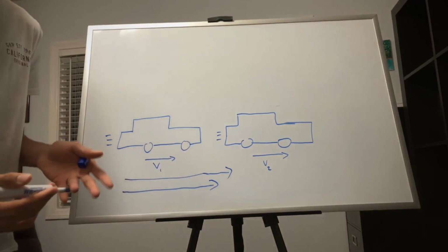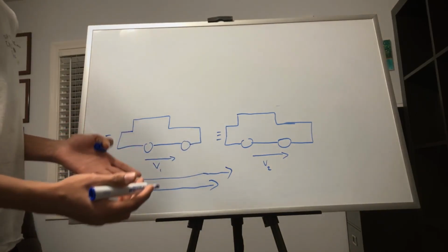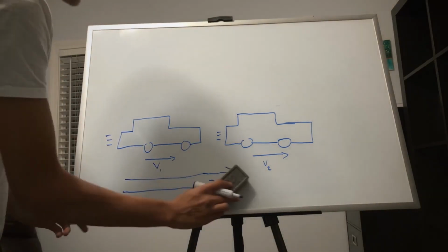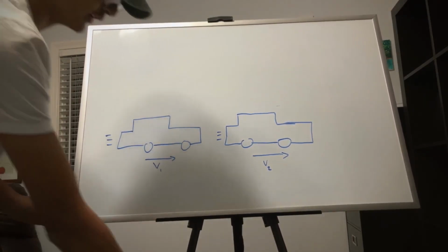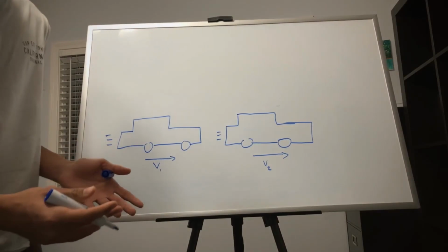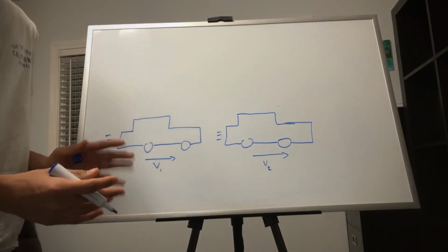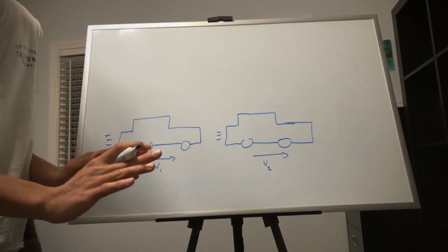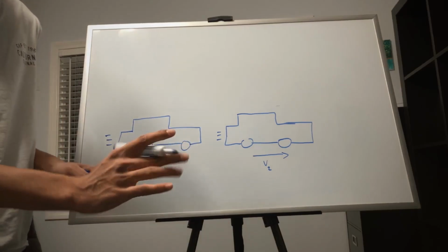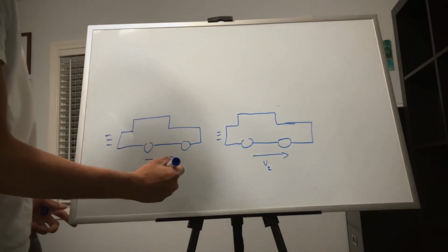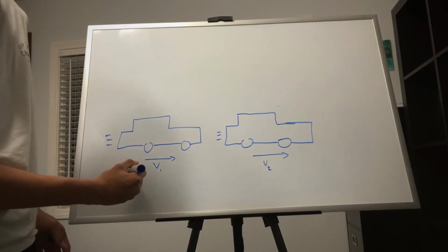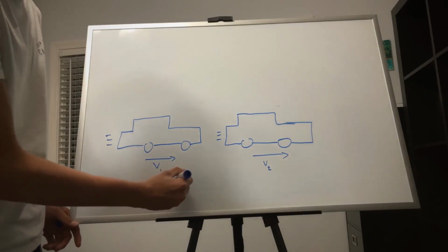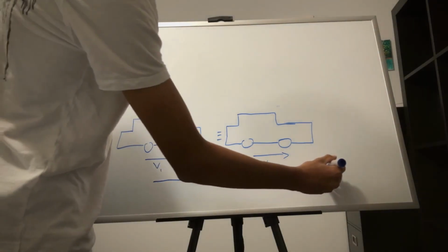So you might think, what if we just use a proportional controller? Wouldn't that work? Well, the problem is that with a proportional controller, if we're changing how much we're pushing down on the pedal, our car position is going to go from being right here to speeding up past this car.